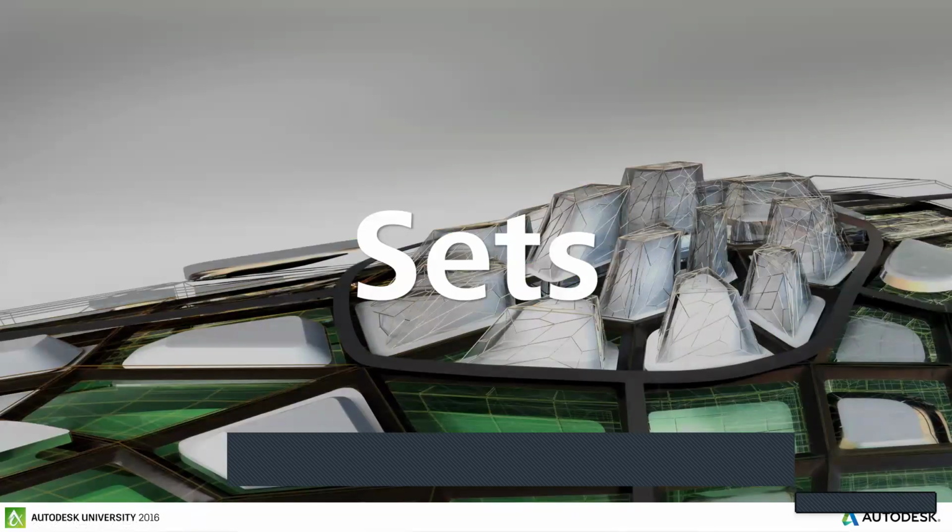Sets are something you use if you are working particularly with multiple element clashes, like, now I will run clashes between models, right? Architectural will have a clash with certain other disciplines, but sets come in handy when you want to check a particular element to element clash. For example, one category of clash within the architectural model will be walls, and another category within the structural model would be beams. So if I need to run the clashes between walls and beams all together, to see how many clashes there are all over the project, then I will create them as sets and work with them. So that is a particular element versus the other element clash. That's where the set comes into play.